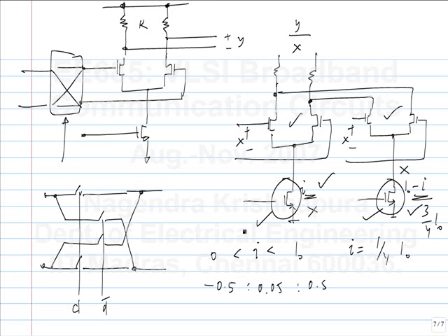Yeah, that's correct. Yeah, so there is a problem here. Firstly, if we change the tail current, the linear range of the transconductor is also changing. So there is definitely an issue with nonlinearity. You just have to simulate it for your particular input voltage and see if it is linear enough.